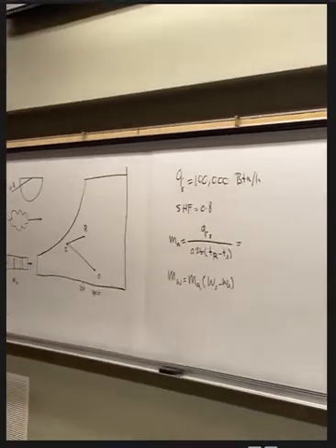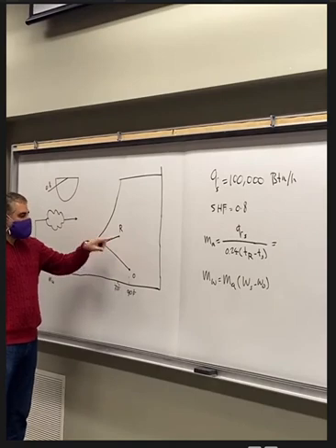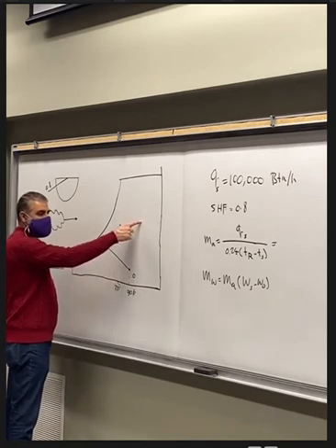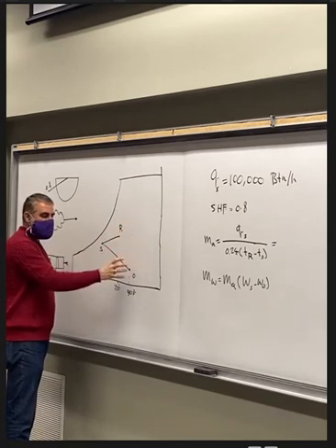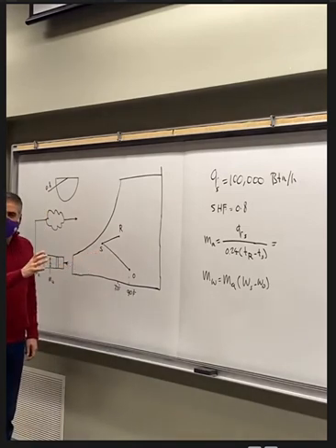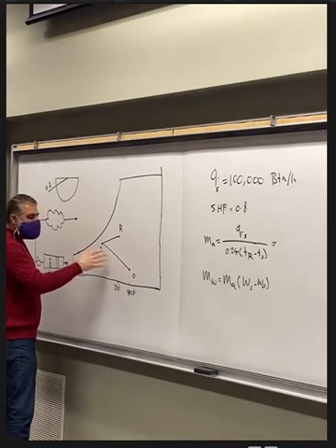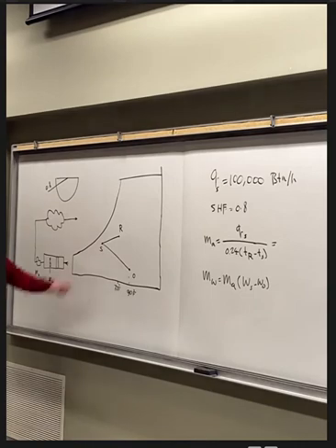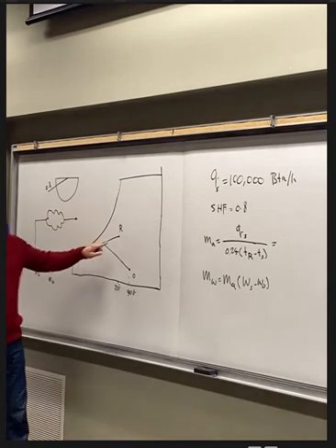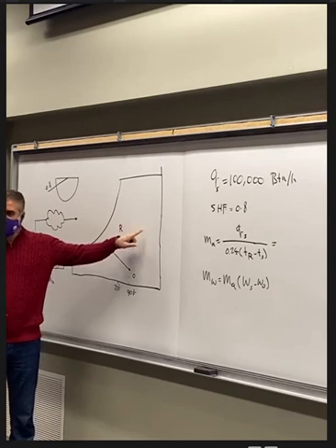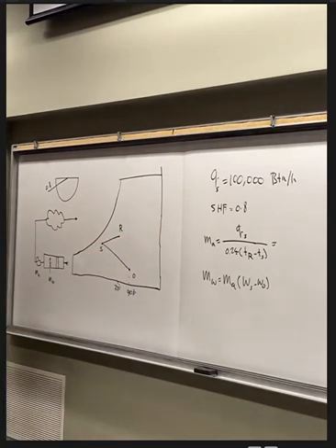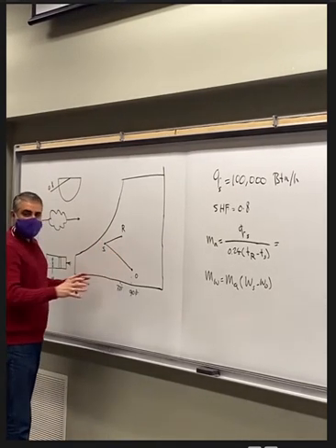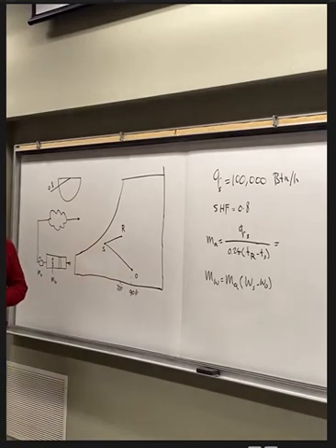So the location of the outside air point and the room point for this question here is very important. If O was located here, the solution might be totally different. So that's why you need to draw the points on the chart first, and you think about the proper process that you have to follow in order to supply air to the space. So in summer condition, we need to supply the air at lower temperature. In winter condition, we need to supply the air at higher temperature. So first keep in your mind, is it summertime or winter time? And also the location of the points on the chart. Based on those, you can decide what is the proper air handling unit that you need to design for your question.